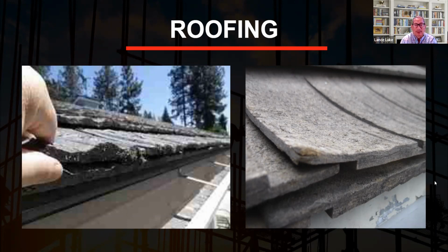Now, there's also a manufacturer who made flat wood shingles that didn't look rough, like rough sawn lumber for cedar shake or shingles, and it looked flat like the photo on the right. But look what happened. The edges start getting worn, and it's like if you cut cardboard and expose it to water, guess what? The end starts curling and swelling up, and that's what happened with these bad roof shingles. So this is all defective material.